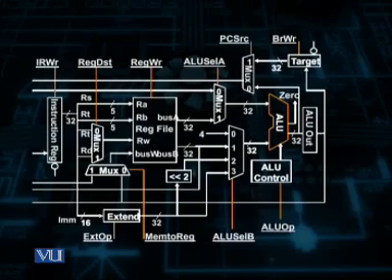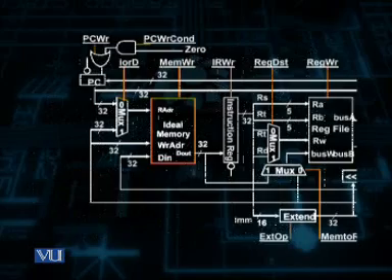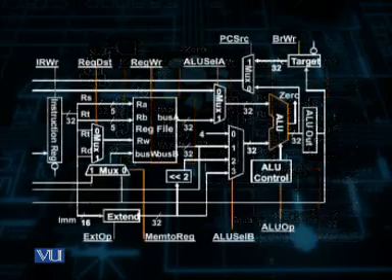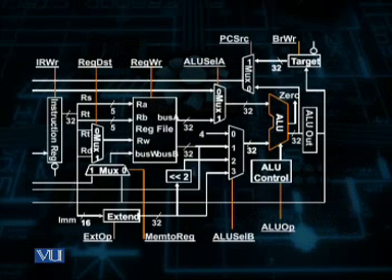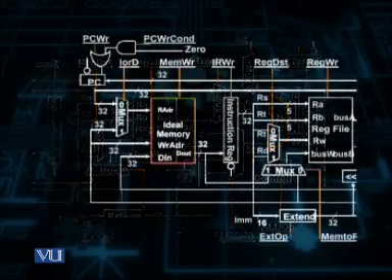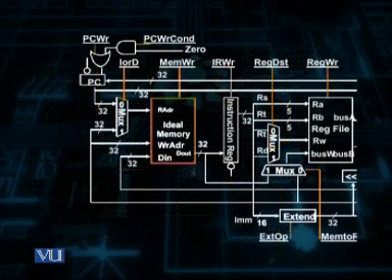Whereas in case of the store instruction, memory write is asserted, as the ALU out register output is wired to write ADR, which means the write address input, which is again shown here, and bus B of the register file is wired to data in, which is the data in to the data memory. Because in case of the store instruction, the data write is performed, and in case of the load instruction, data read is performed during the 4th clock cycle.